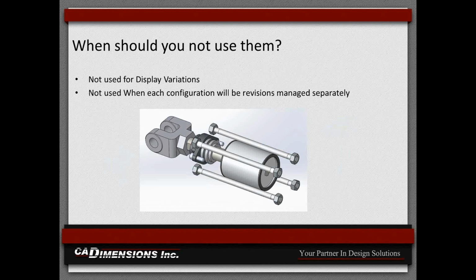When should you not use them? As I mentioned, the revision thing, that's a perfect scenario where you would not want to use configurations. And the other one is for display variations. And I've seen this through the years where folks will create configurations to do things like changing color, hiding or showing components. That's really not what it's for. There's display states in SolidWorks, and display states are used for display variations.